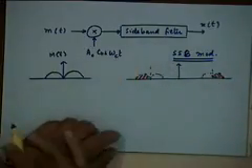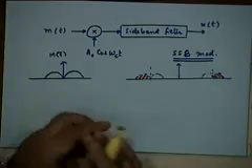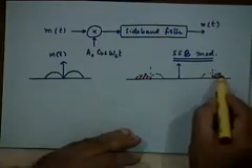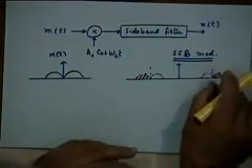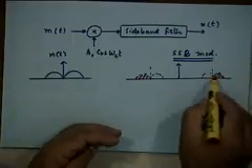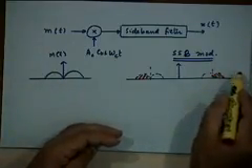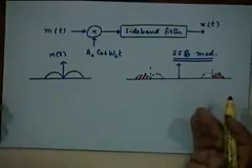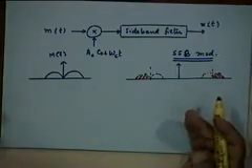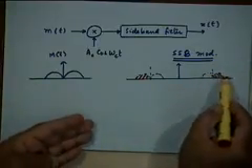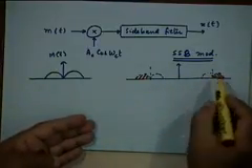So if you want to retain this part, what kind of a sideband filter should you have? A high pass filter, right? Or we should have a band pass filter here, which will only pass this portion of the spectrum and reject everything else. Theoretically a high pass filter will do; in practice we'll of course use a band pass filter. Theoretically a high pass filter will be able to separate out the upper sideband from the lower sideband, right?